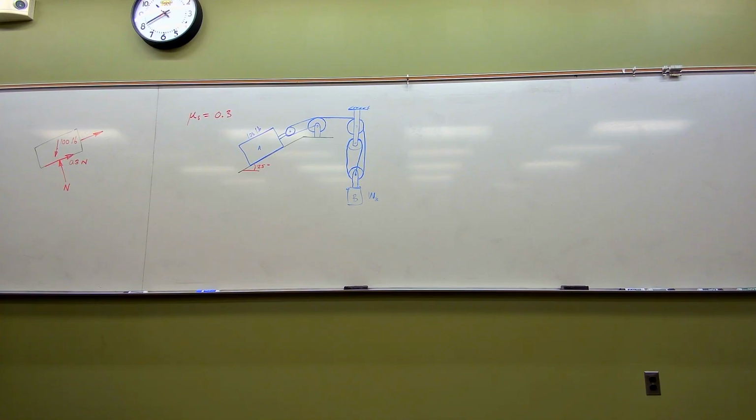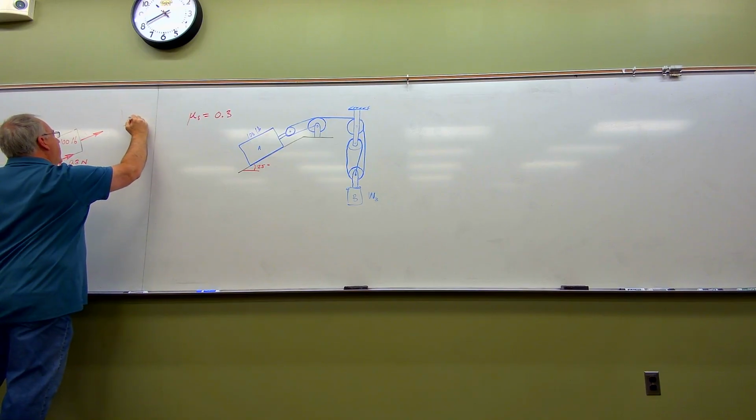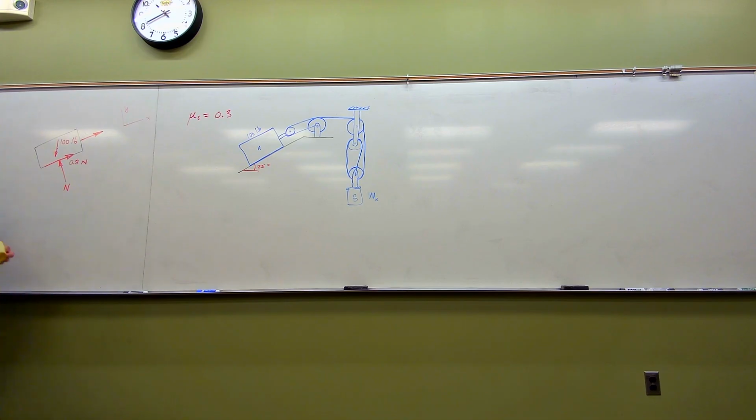easier. Folks, I want you to look at this. Notice how I've got a force here pointing in that direction, another force pointing in the same direction, and I got a force here that's normal to that. I got three of my forces that are following a directionality that would make it seem logical to include an X and Y axis system that looks like this, which in doing that, I just made this force here and this force here purely X directional. I just made this force here purely Y directional, which means my math is going to be easier to deal with these forces. The only force I've got in my entire system that is not falling right on the X or Y axis is going to be this force right here.